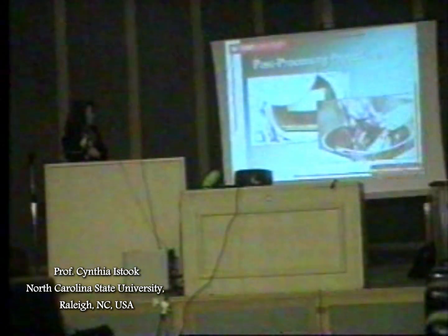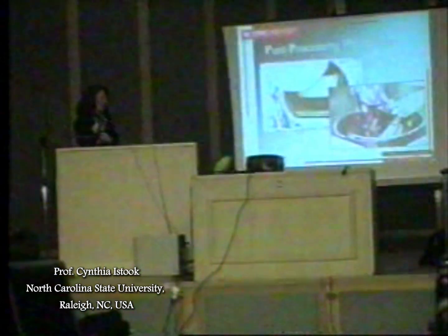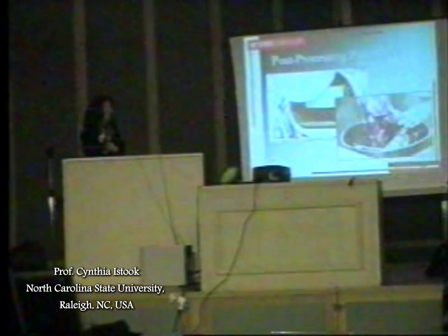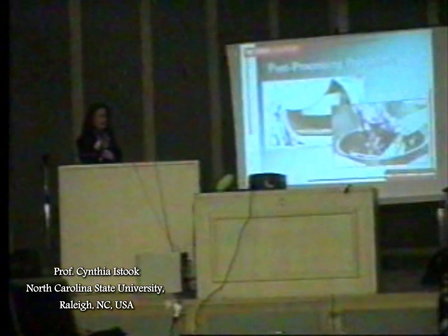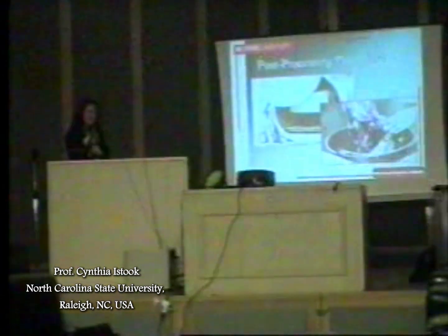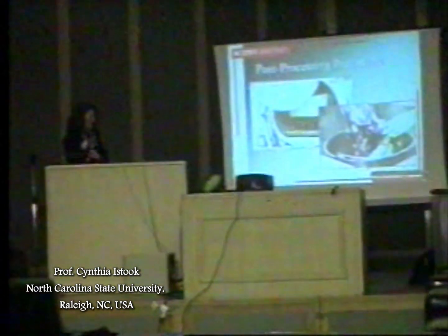And then ultimately, we have to post-process the fabric that we print. It has to be steamed to set the color. We have the color reactive fiber, and we have to wash out the excess pad chemicals that have been padded onto the fabric and the excess dyes.